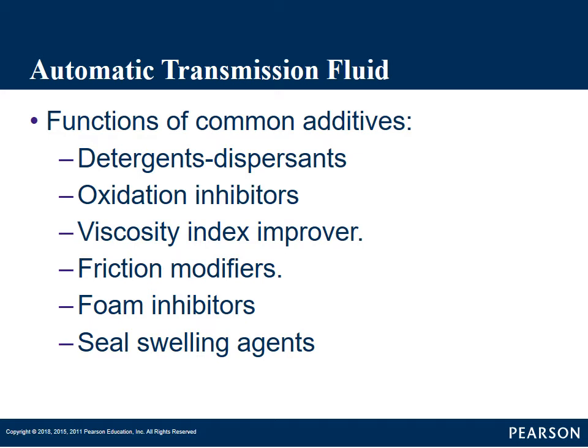We have foam inhibitors in there to prevent air bubbles, the fluid foaming. You can still get fluid foaming in certain circumstances. Why we don't want it to foam is that's air bubbles.